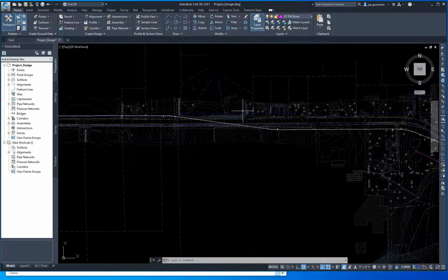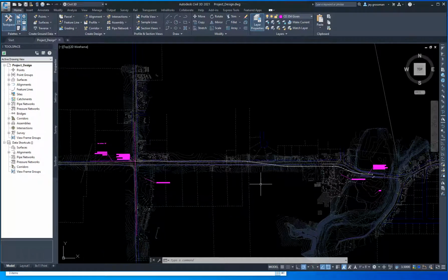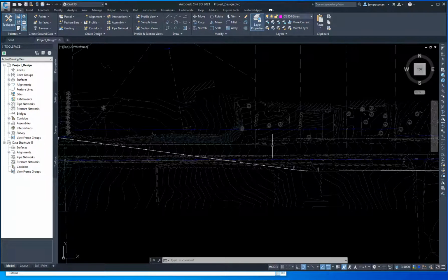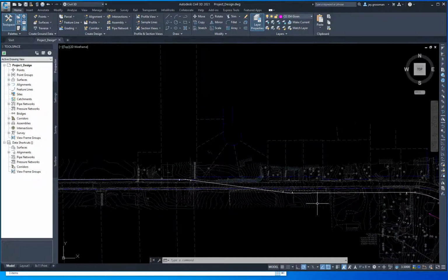You're going to see later, you can check these as you go through to see if you are. Well, you have to create a corridor, and I'm not sure we're going to do that for this. But you're going to offset how far off of this line. This is your center line. You'll offset your lane width, and then your shoulder width, or your curb if you're using curb and gutter. And hopefully that misses all the houses as you go through there.